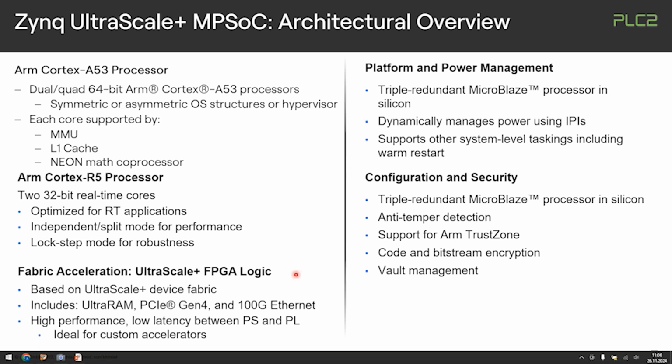And the fabric, as we said before, there comes the IO, very typical for Xilinx devices, the transceivers on the high-speed side. These would come in with up to PCI Express Gen 4, or you can build up 100G Ethernet interfaces on that fabric side. Of course, the PS part, the CPU fixed IP part, is not capable of doing these high performance level things. So this is where you have to actually integrate both elements into your complete design.